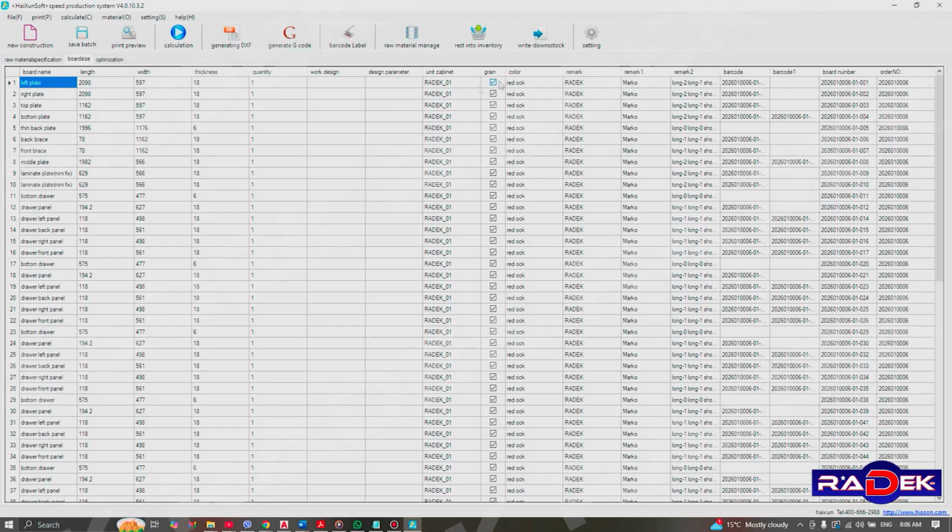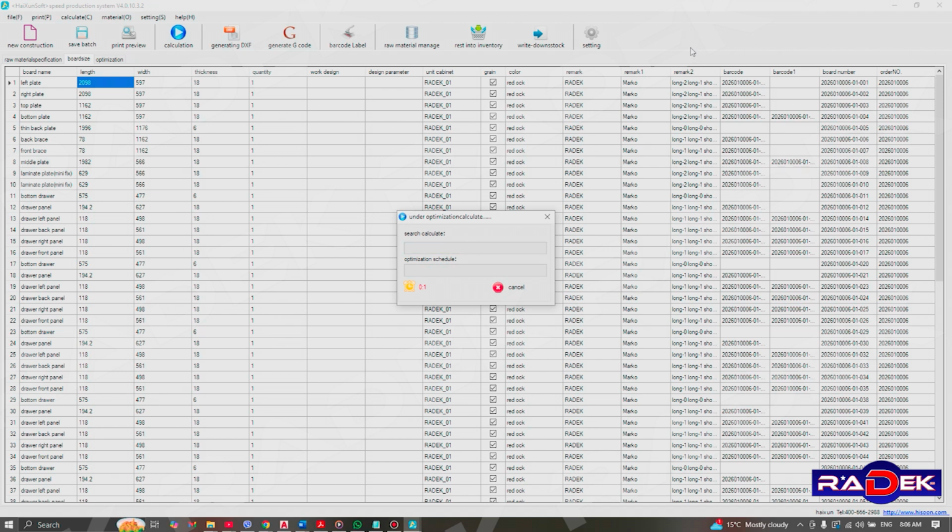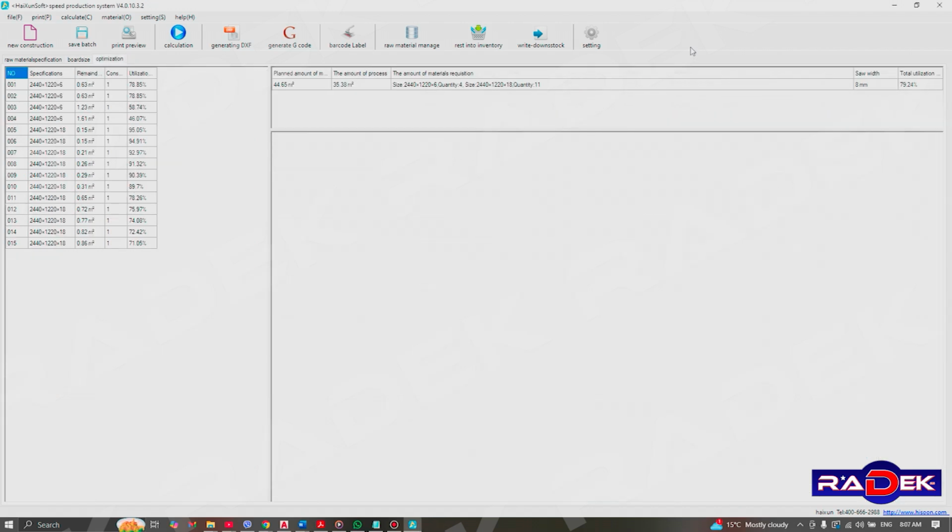After the optimization is complete, the program will automatically transfer us to the optimization section. In this section, we get a detailed visual display of the orientation of the elements, their position on the boards, and the efficiency of the material usage. Here we will also select the appropriate tools, adjust the processing sequence, and generate the final G-code. Before we do that,